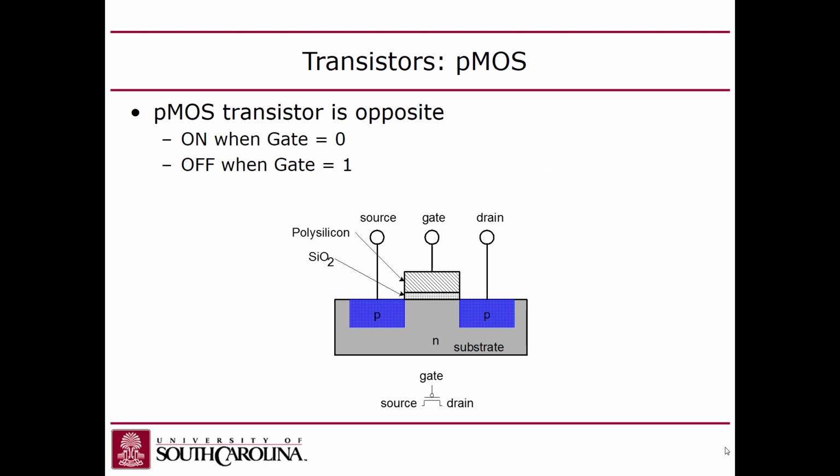Now you might say, wait a second, hold on. The substrate is the whole chip, right? The whole bottom of the chip. How is it that you can have a different substrate for N transistors than from P? It's because with PMOSs or PFETs, this part is actually called a well that's actually buried. So it's kind of weird. You've got the whole chip is a P-type silicon. Then you have an island of N silicon in there, and then islands within an island, these 2 diffusion areas for the source and drain. You guys with me?